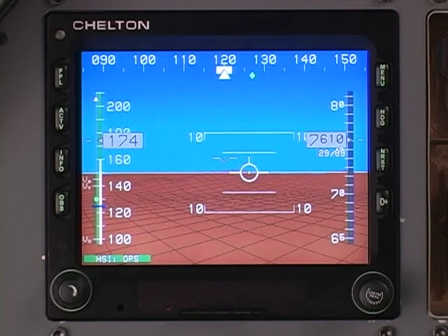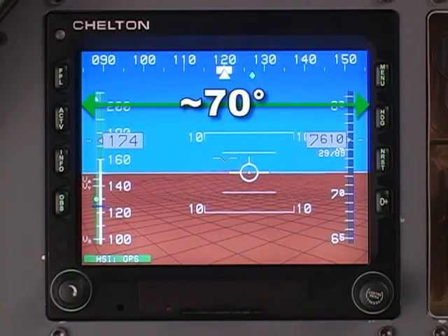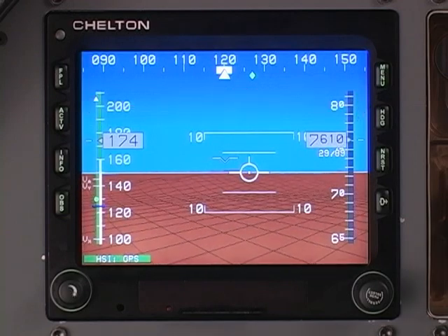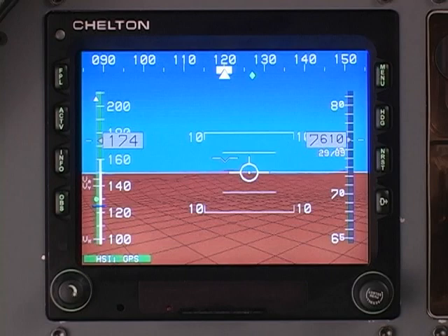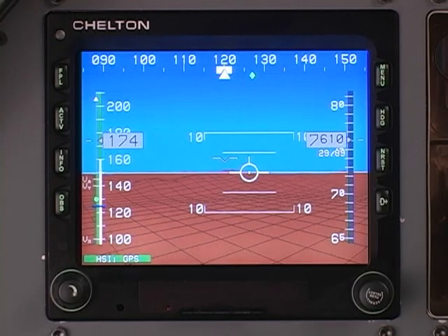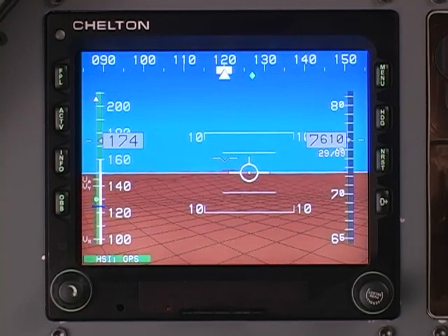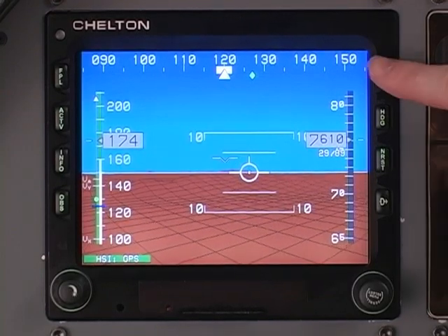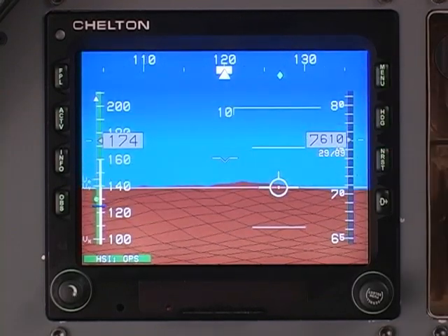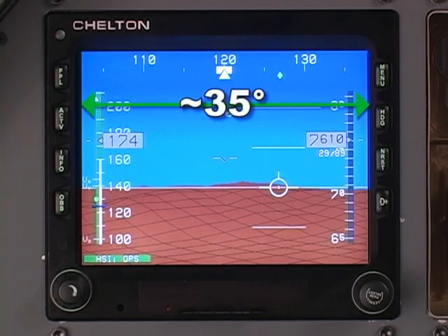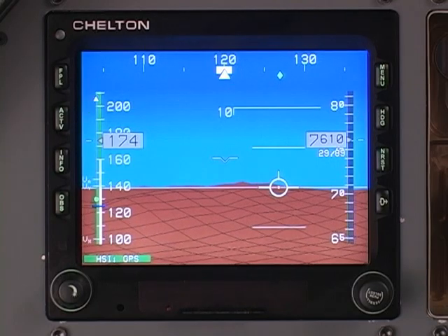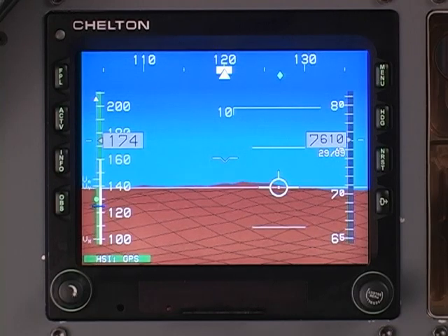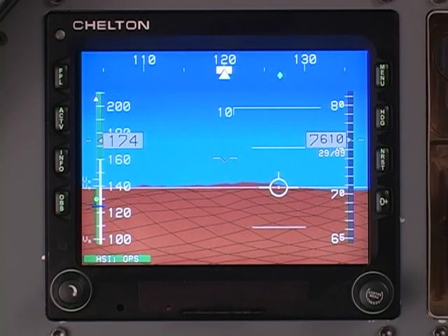In the normal mode, the PFD's field of view is similar to that of a wide-angle camera lens. This is most useful for the majority of flight operations, since aircraft maneuver primarily in the horizontal plane. It does, however, diminish the visual impact of terrain. The zoomed mode most closely matches the field of view of the human eye, and therefore makes the terrain display more closely resemble the real-world view ahead of the aircraft. This zoom setting is useful for landings, as the runway depiction is expanded.